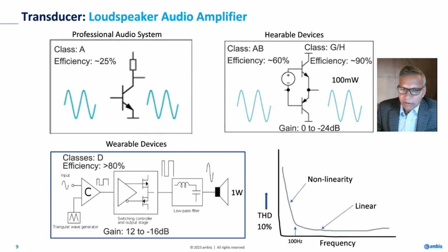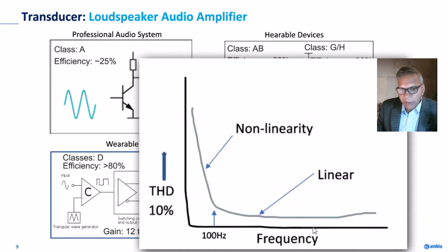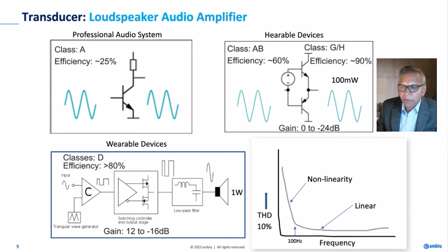How will you characterize acoustics? One way is plotting frequency response versus distortion. To see how well your acoustics is behaving, given a requirement for meeting certain lower frequency characteristics, one way is to take the distortion, THD, versus a swept frequency and then plot it. That will tell you how well your acoustics is behaving.